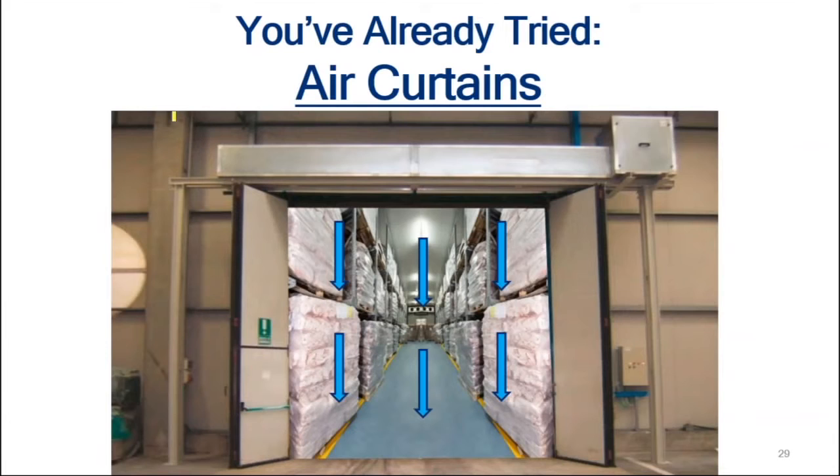The third potential solution for keeping moisture out of your cold storage area is air curtains. A curtain of air, a high velocity airstream across the entire door. Whenever the door is open, this is on. We're moving air down across this opening at 3,000, 4,000 feet per minute. And in doing so, it creates a pressure that resists moisture to a degree, but mostly the air from infiltrating into the air curtain, into the cold storage dock.